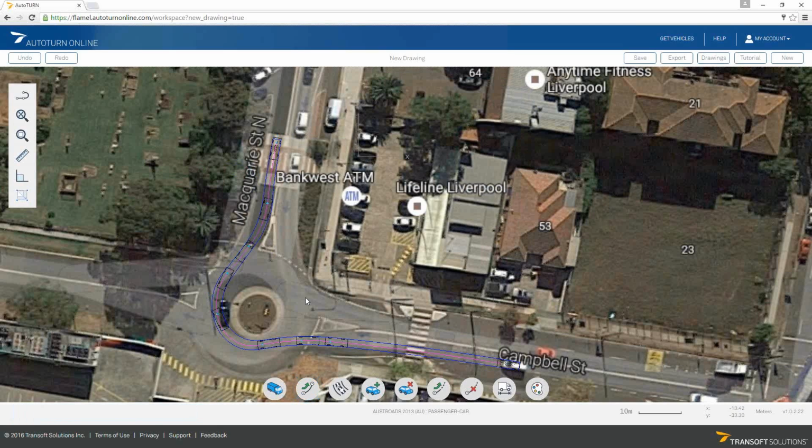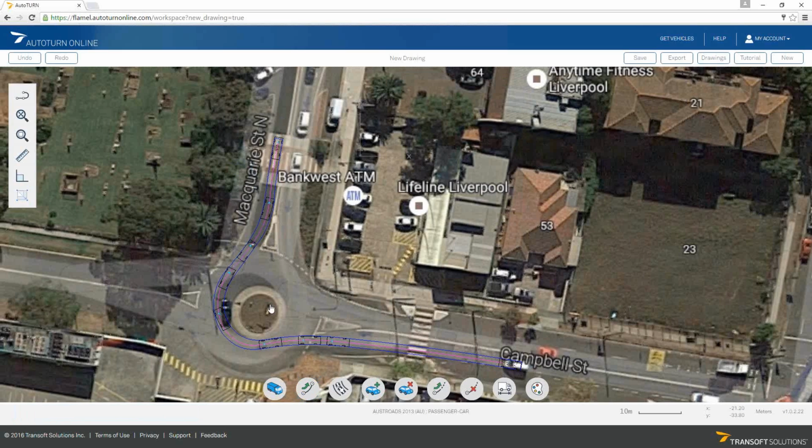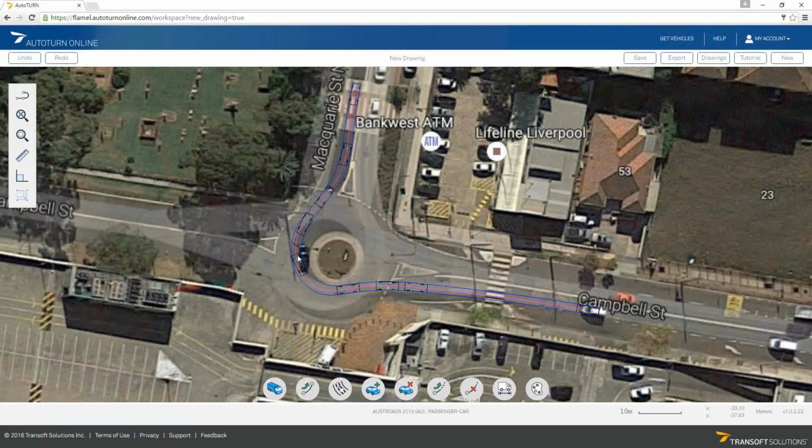If you have your CAD drawing, your 12D drawing, you import it in, you can indicate the centerline geometry that you would like this vehicle to follow based on the fastest path analysis, and use that as reference to generate a simulation. The only thing you need to take into account is that by doing that, you're only taking into account the turning characteristics of the vehicle.